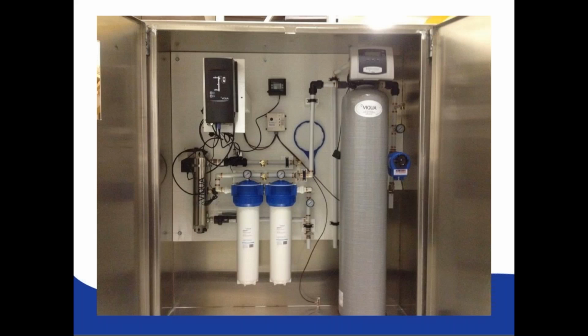So here's an example of a fairly simple UV installation. You can see the solenoid valve, which is the black component immediately below the black controller on the left, is immediately located on the outlet of the UV chamber. We can see the chamber is installed vertically. The electronics are up nice and high where they're less likely to be sprayed by water, etc.